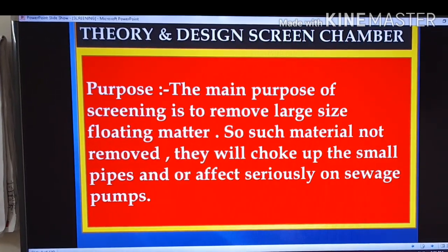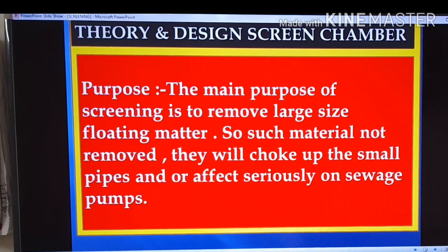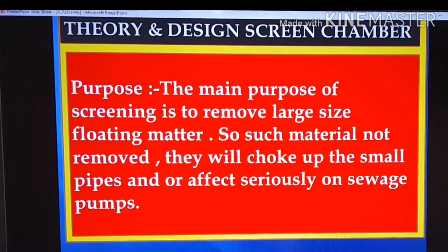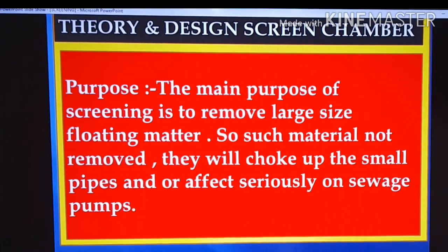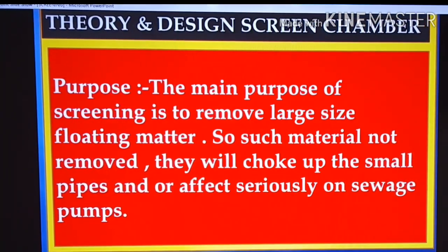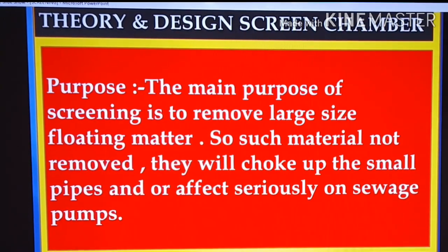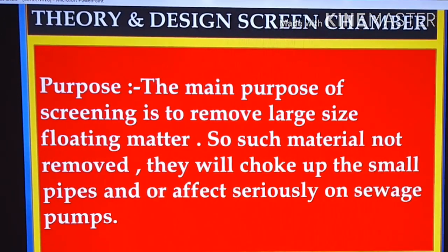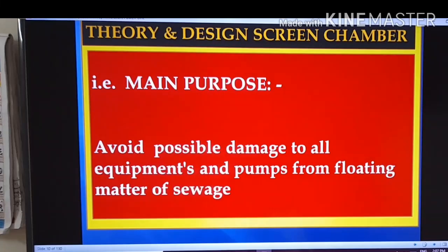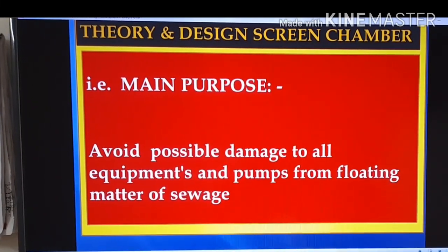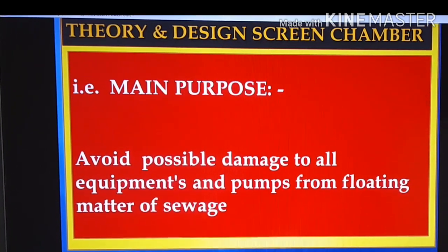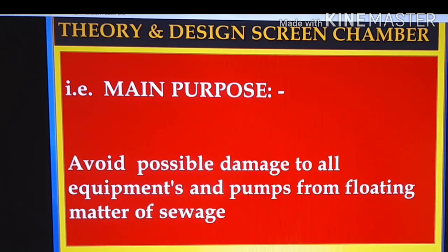Next, theory and design of screen chamber. The main purpose of screening is to remove large size floating matter. If such material is not removed, it will choke up the small pipes and seriously affect sewage pumps. That is, the main purpose is to avoid possible damage to equipment and pumps from floating matter of sewage.